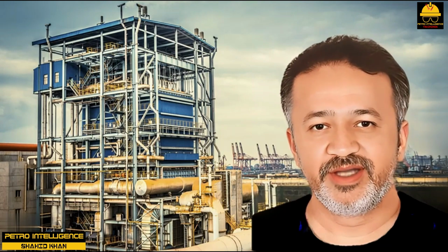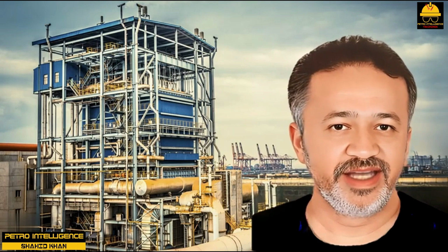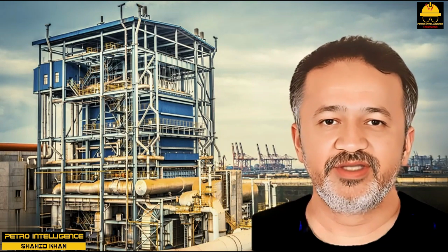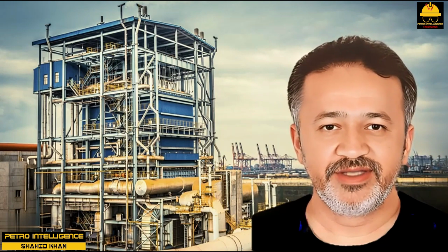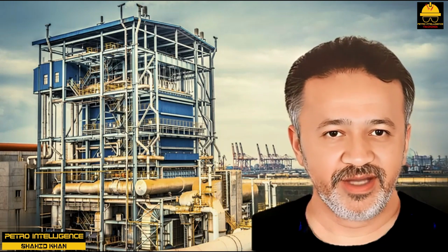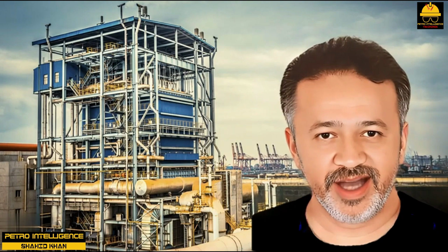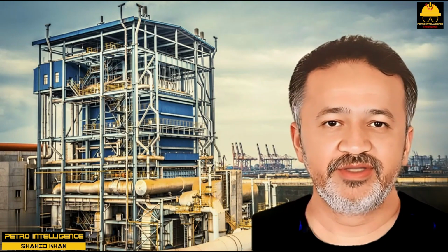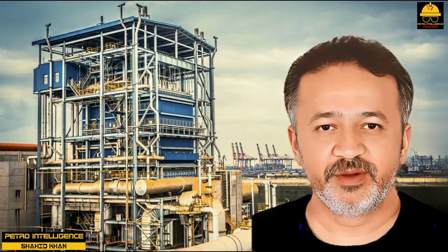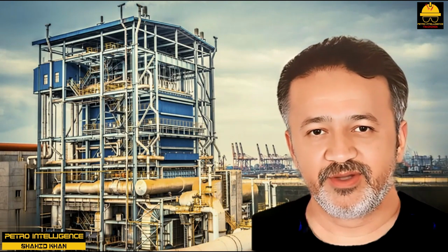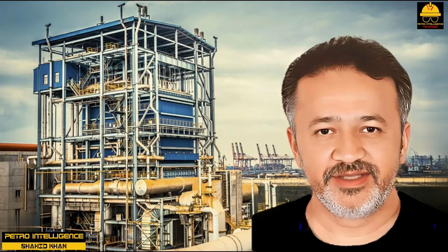Our more direct experience of this comes from current practice in the United States, but we have also seen evidence of similar applications in Australia, as discussed in a recent article on the subject of crude preheat exchanger train redesign. We have also heard of a case where a heat exchanger was retrofitted with a helical baffle bundle and the shell side fouling actually increased. The client theorized that, as the angle used to slope the baffles can apparently be varied by the designer according to service conditions, the angle for the baffle had not been correctly selected.